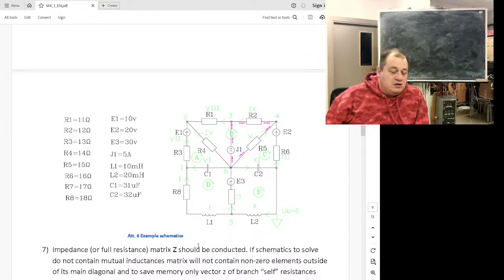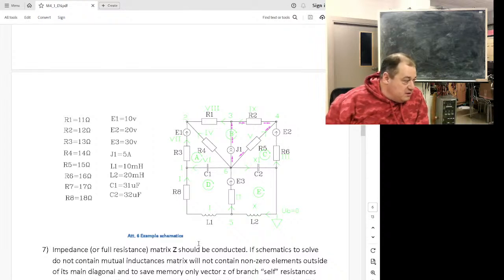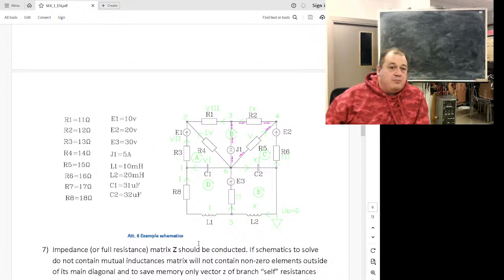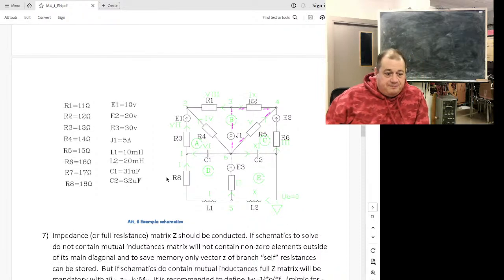Next question, the impedance matrix. Here, resistance, better to use the term impedance, will have real and imaginary parts. For elements not storing energy, the digit will be real. For elements able to store energy, either in an electrostatic field as a capacitor, or in a magnetic field as a coil, there will be a complex value.